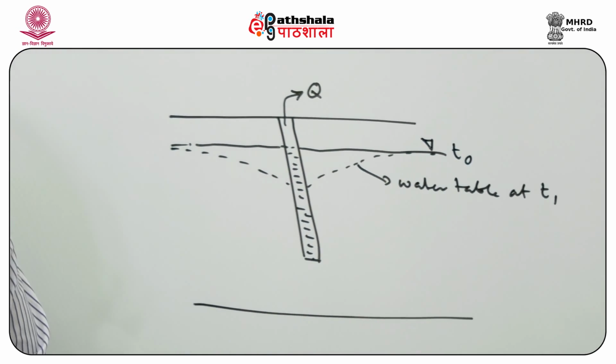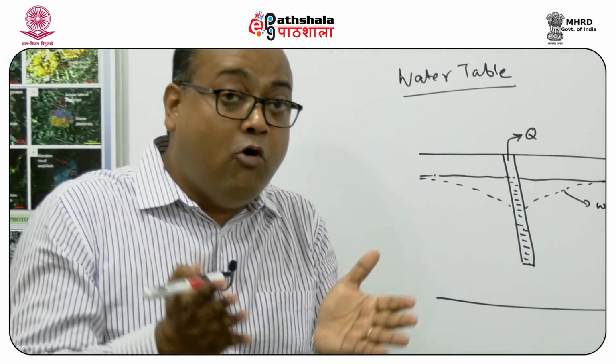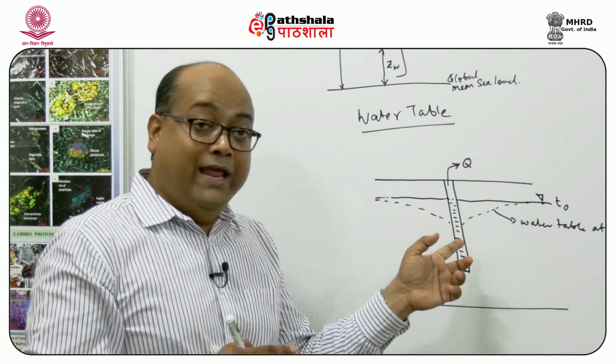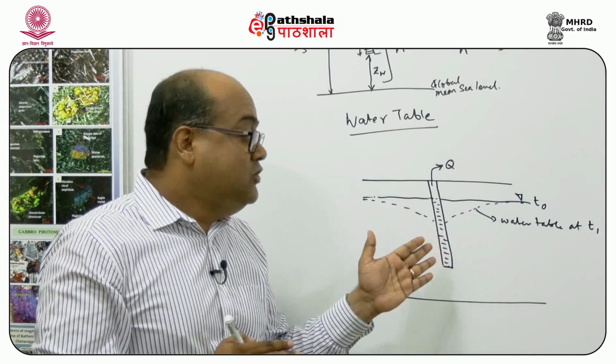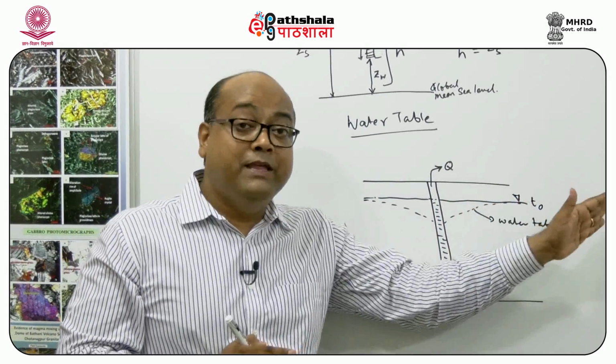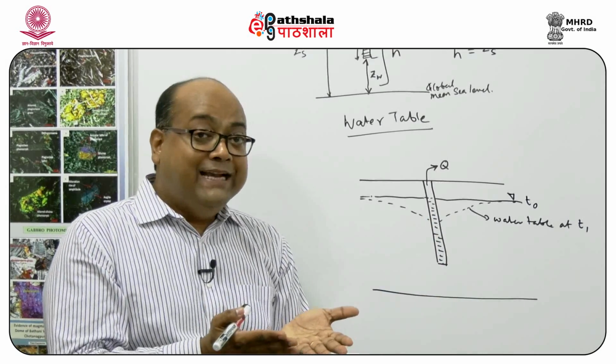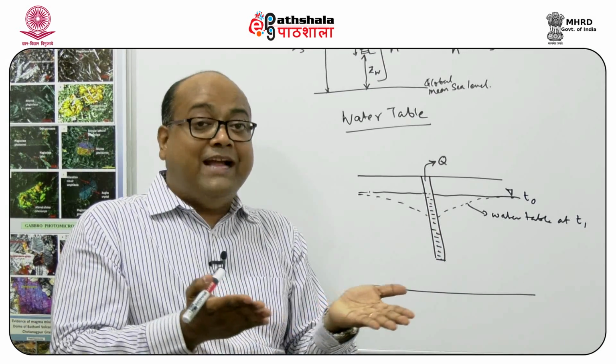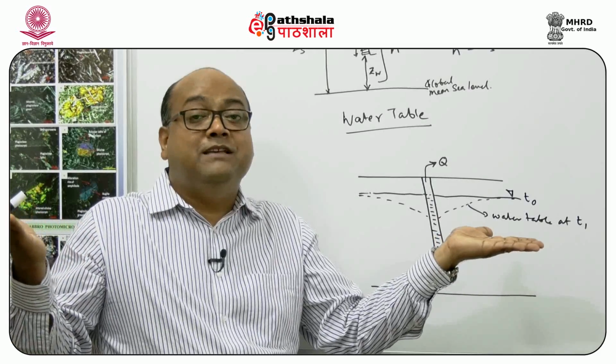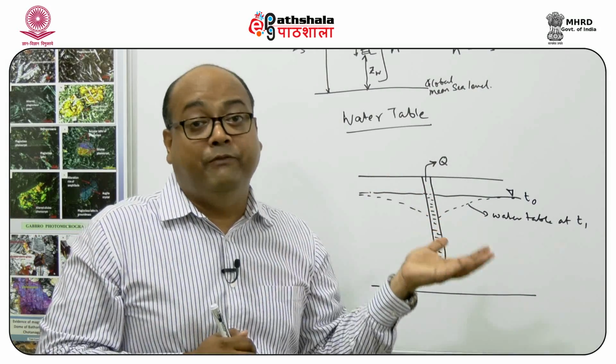What we can see is that there is a depression forming near the well, and as you move away from the well from which pumping is taking place, the water level becomes very similar to the static level, or the level before pumping.